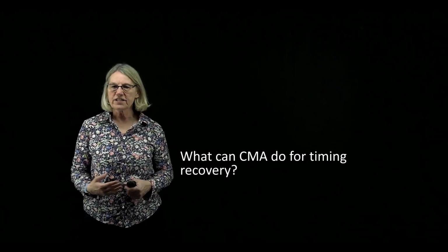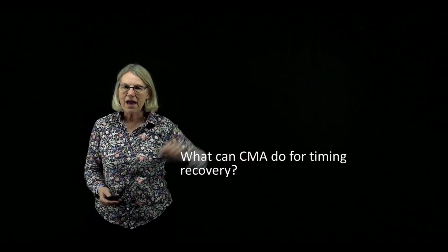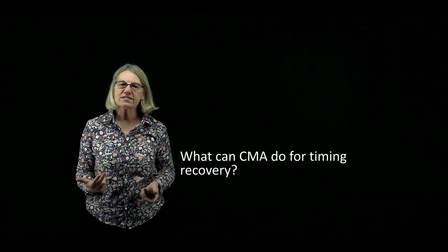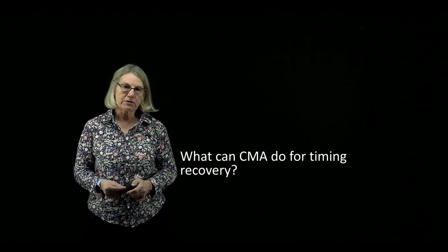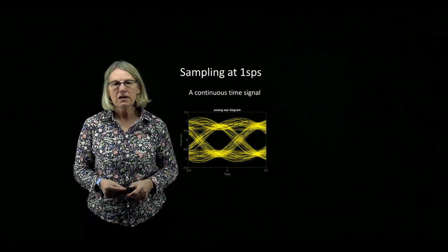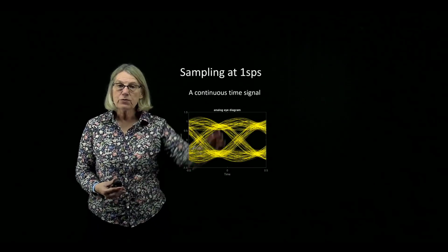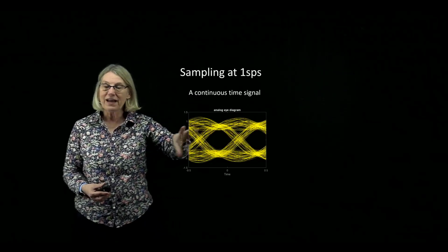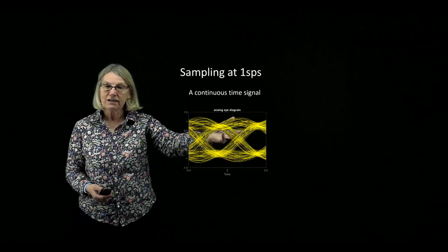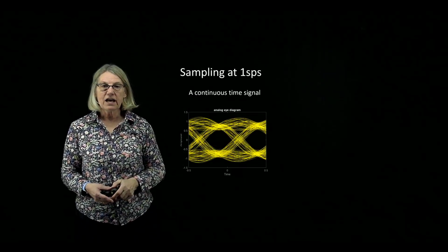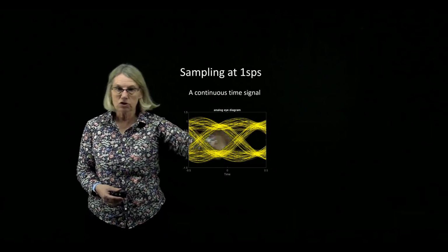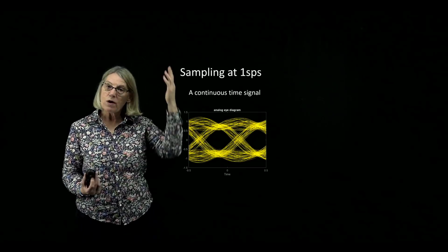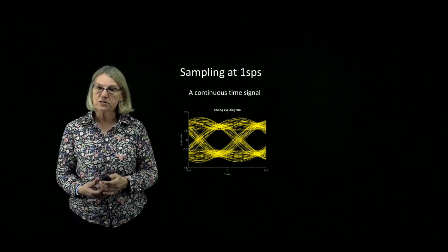We're talking about the constant modulus algorithm, CMA, and we're going to discuss now how the CMA can help us recover timing in the laboratory setting. So suppose that I have a continuous time signal. Here is my example, my raised cosine 25% pulse that I am sampling way over-sampled, so it looks like continuous time. And suppose I want to sample this at 1 sample per symbol.